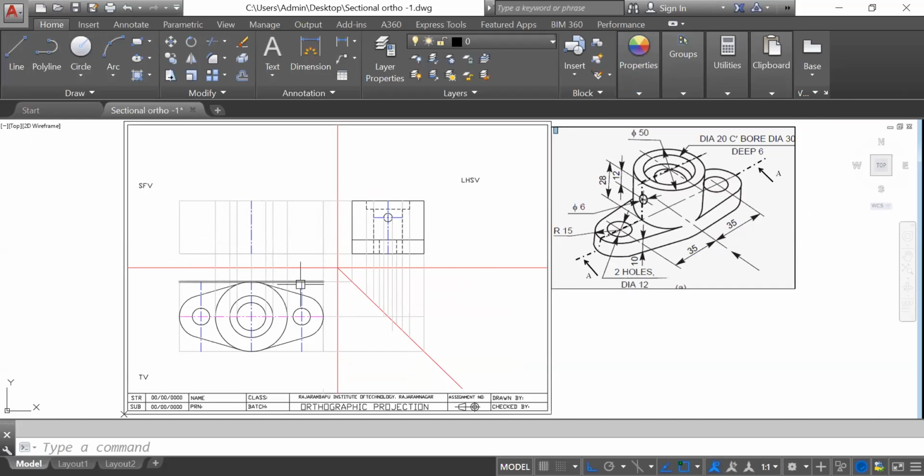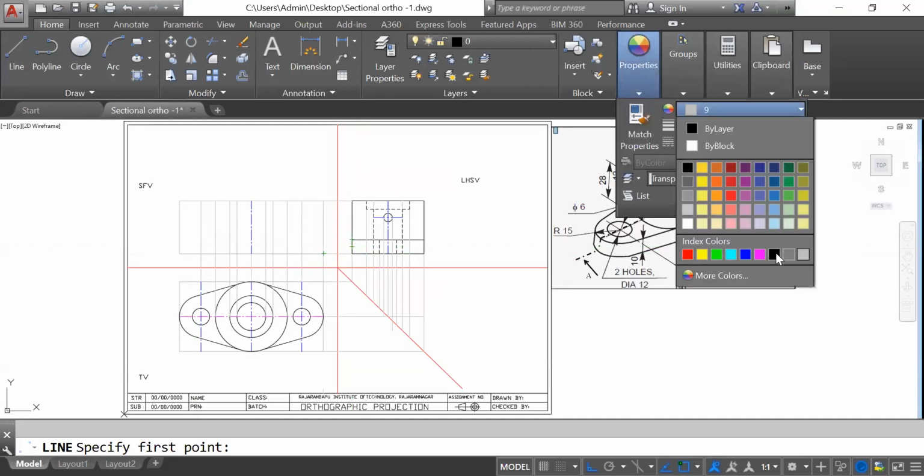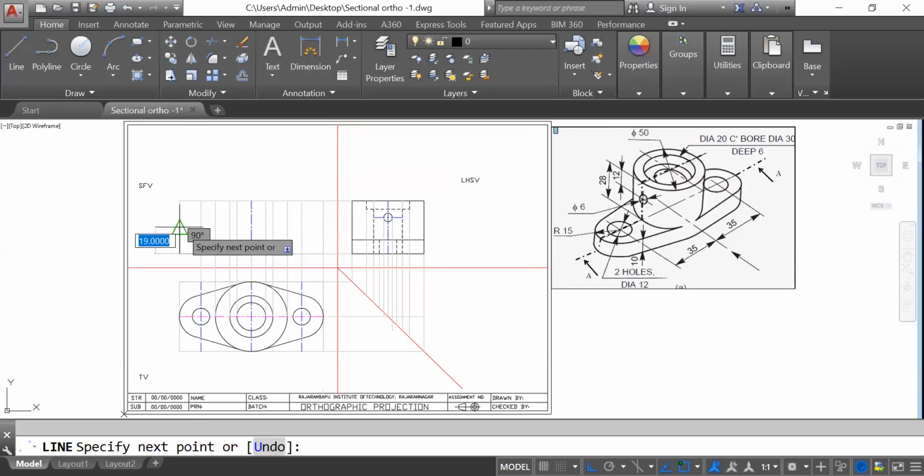After that, next part, you can take the projection for these holes also. Okay. You can take the projection for these holes, or you can take stepwise projection also. Okay. So first of all, if you see, this part is visible, this step, this is a rectangle, right? So having thickness 10 mm. So this we have to show. So how can we show? We can take the projection, or you can just take this black color and just take this 10 mm. Okay, and then draw this one 10 mm depth. Okay, after that the cylinder is visible.